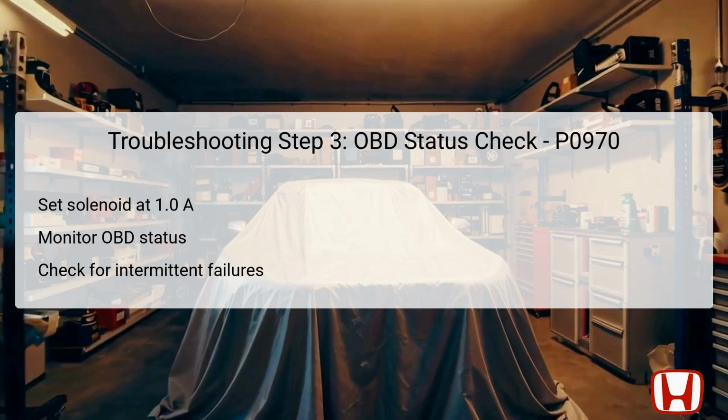In step 3, verification of the OBD onboard diagnostics status takes precedence. From the clutch pressure control solenoid valve control menu, set the AT clutch pressure control solenoid valve C to a current value of 1.0A utilizing the HDS. This setting allows for a thorough inspection of the solenoid's performance under specific electrical conditions.